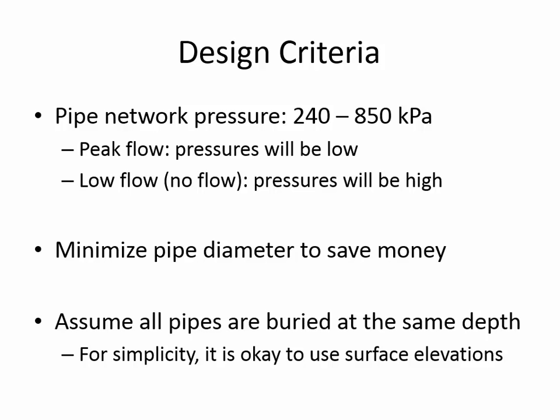And so in the second phase of this design project, once you draw all of the pipe networks, you need to evaluate the network at two different conditions. At full design flow rate, you're going to make sure that the pressures don't go too low. So if you've drawn all your pipes and you're telling it, tell me what the pressures are at each of these points when I've got my maximum design flow coming out at the outlets, and you see that one of your junctions has a pressure of like 50 kilopascals, what should you do to the pipe that's connected to that junction?